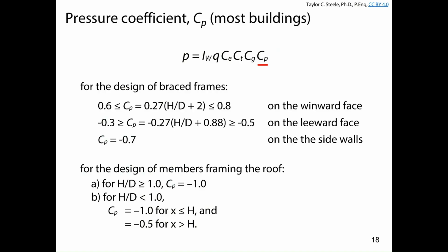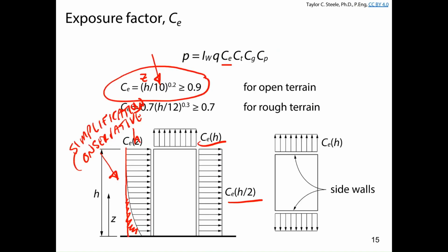If we go back here to our exposure factor, for wind in this direction, we're going to be using the width of the building that is along wind or parallel to the direction of wind. And h here is equal to the same little h. Okay, so it's a ratio of the height of the structure to the width in the along wind direction. And so the higher the h over d ratio, the more the wind is going to affect our structure.